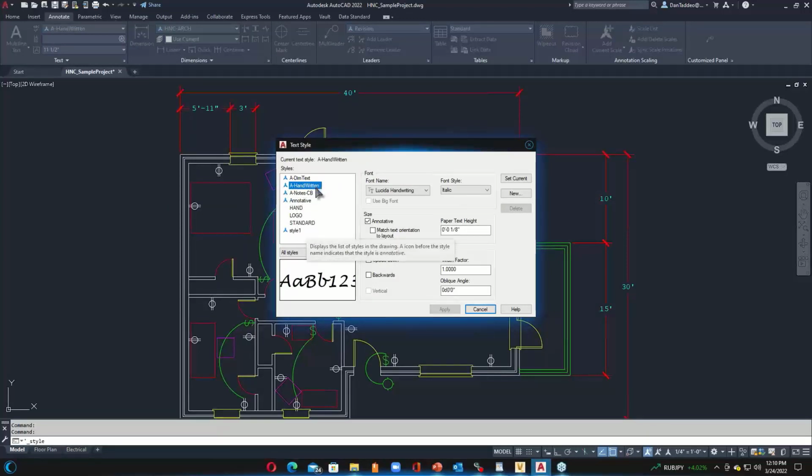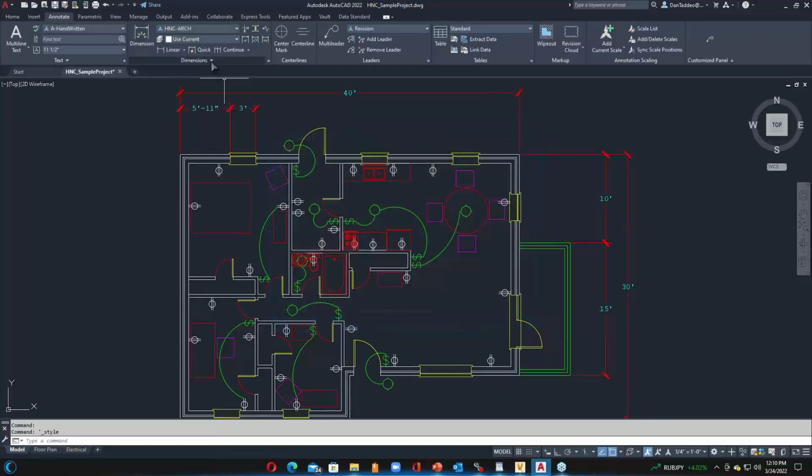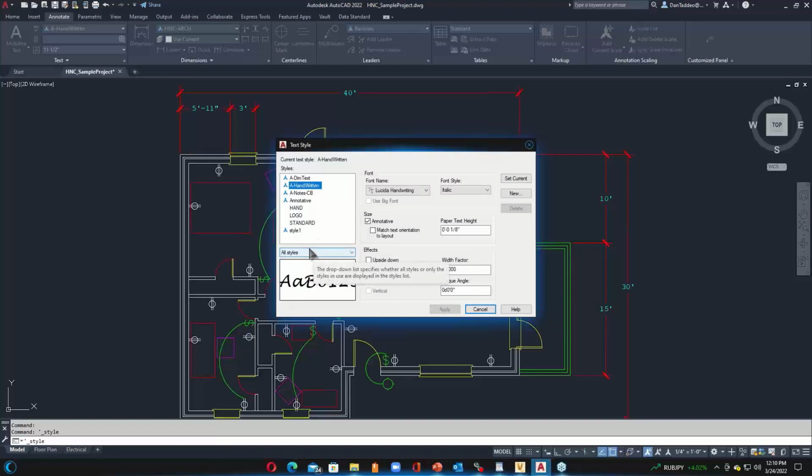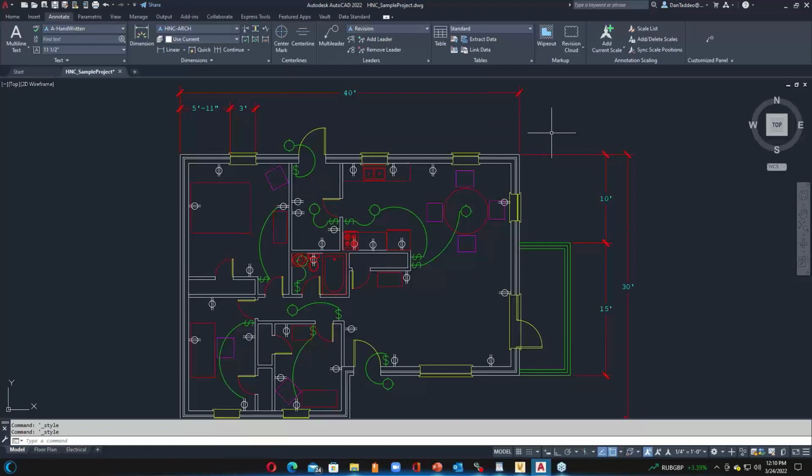Maybe I have some notes that utilize the handwritten styles here. I have a dimension text here, and they have different fonts. These things take time to build. If you expand that and think about dimension styles, leader styles, table styles, it adds up. And if you're having to open a brand new project file, starting with populating all of these, you're wasting a lot of time building out your standards in each of those drawings, correct? So what can we do to speed up that process?